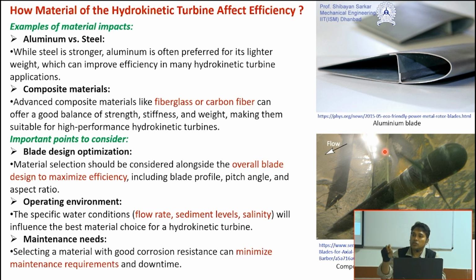Corresponding to 0.5 meter per second, you have calculated that much amount of load will be withstood by this turbine blade. So accordingly you have selected the thickness of your blade and your material, thinking okay fine, that much amount of load it can withstand. But suddenly you find it has become 4 times, 5 times. So you have to check what your factor of safety of this material is, whether it can withstand this fluid velocity present in the river or not. That particular analysis you also have to perform before implementation of your turbine. So those are the things.